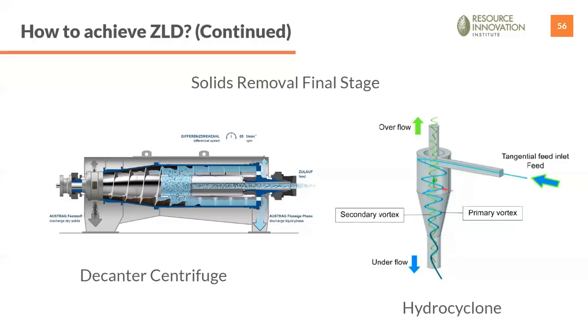In the past, these brine crystallizers were commonly employed as forced circulation crystallizers to concentrate the brine blowdown from upstream concentration equipment. The solids byproduct gives the option of recovering the salts at the end of the ZLD process. The drawback to using crystallizers, as they have been used in the past, is the takedown of the equipment for cleaning and the maintenance